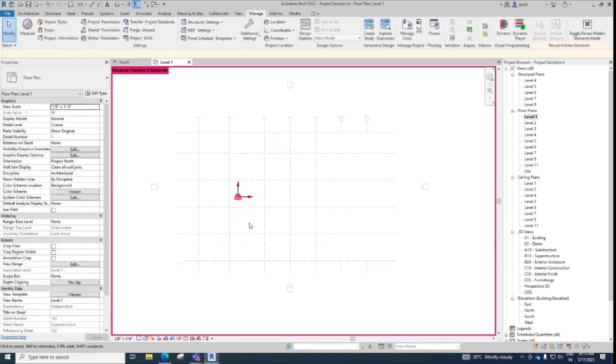Why? Because when you link Revit files or any other file, it comes in with respect to this base point. It is one of the options that you have, to copy with respect to the base point. When we have different files that we need to collaborate on, like different disciplines, MEP, electrical, HVAC, whatever, if we have this base point set at a place that is relevant to the project, everyone can set their base point according to that only.